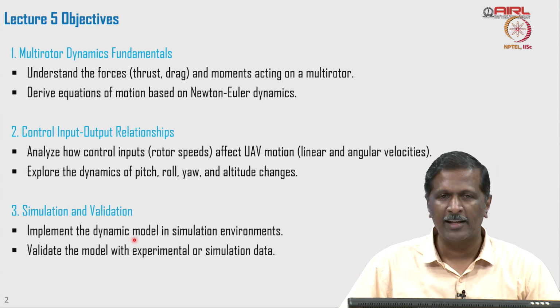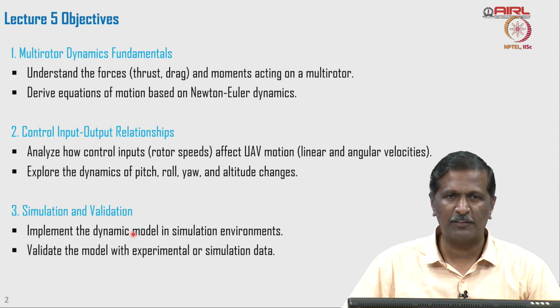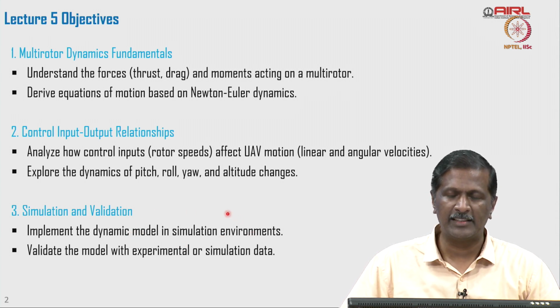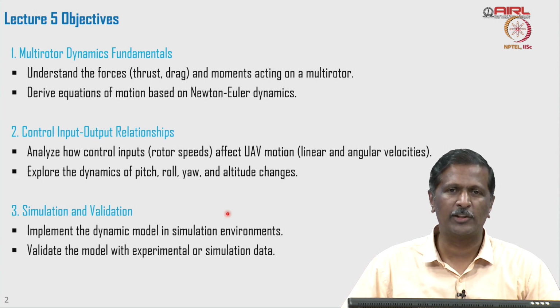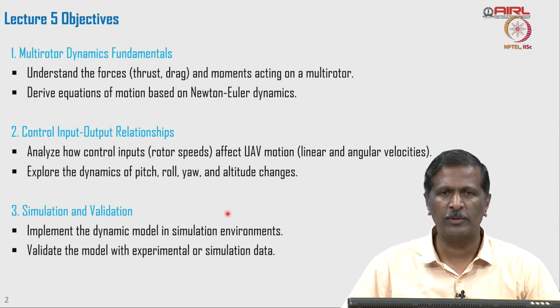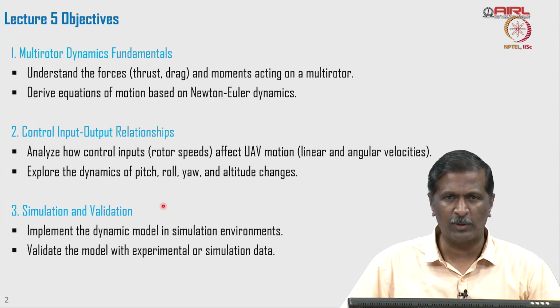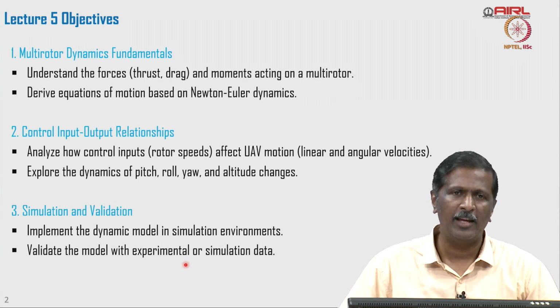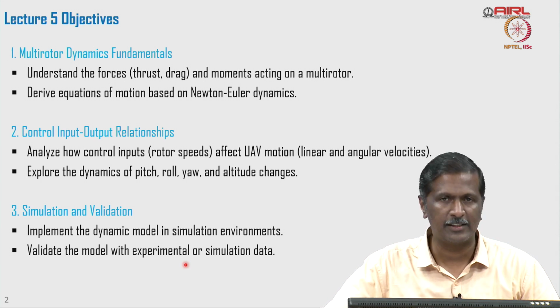For this, we will look at a MATLAB-based implementation of dynamic models in a simulation environment. This simulation environment will start adding sensor dynamics and the context in which the drone is going to fly, so that the response of the drone is as close as possible to the real environment. That is our objective. Once we do that, we validate the response using experimental data. Hence, the future controller and navigation modules, whatever we are building, can be verified before being deployed in the actual system, right?